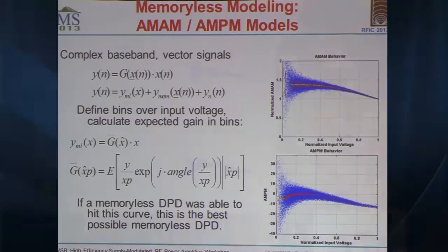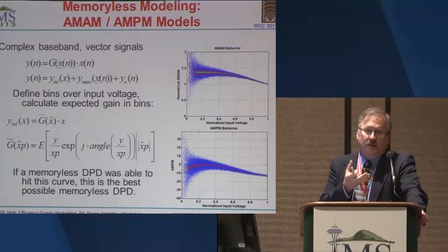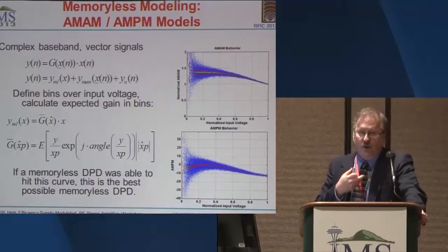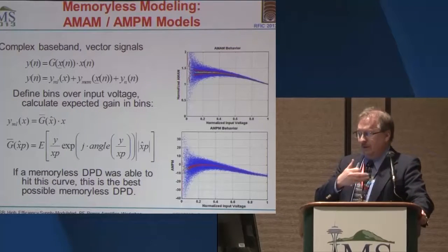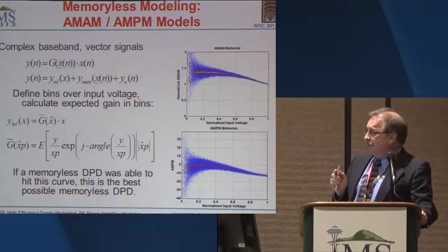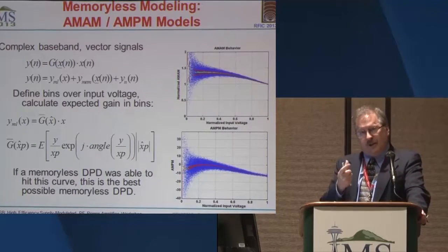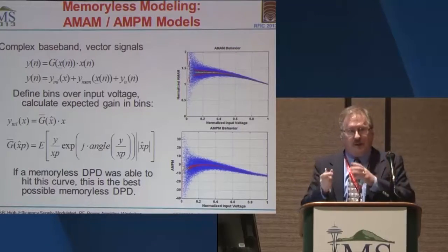So I actually have this non-uniform sampling of the distribution, and that can create a modeling bias, which can actually ripple through the whole digital predistortion and ripple through the memory modeling, and a whole bunch of other issues can show up. So that's one thing. And if I tell my favorite statistician friend, I've got this problem where I have non-uniform samples in space, they're going to say, okay, well, do averages with a fixed number of samples, so it makes a non-uniform bin width.